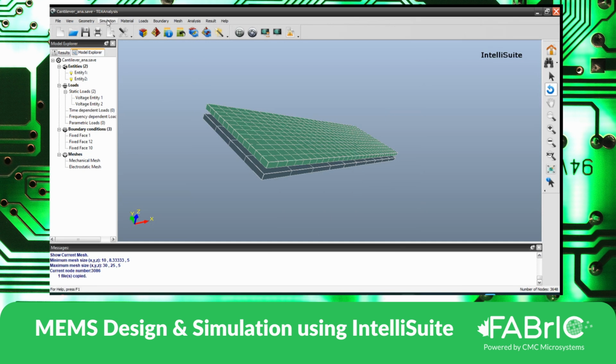We have a question, Dr. Raja. Yes. So Almore asks, for the displacements that you have shown earlier, we have seen maximum values. Could we extract values across a certain line? Yeah, so whatever you saw was actually the last value, the maximum displacement, the last value. So you can get the journey, from what point to the last value, by plotting the graph.